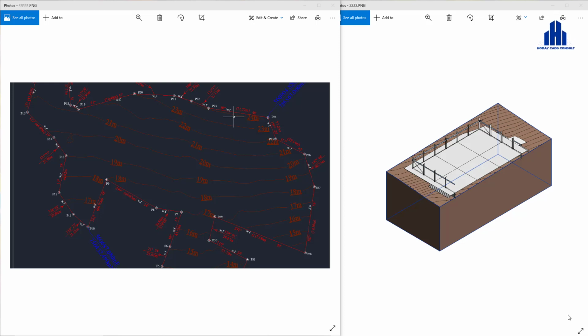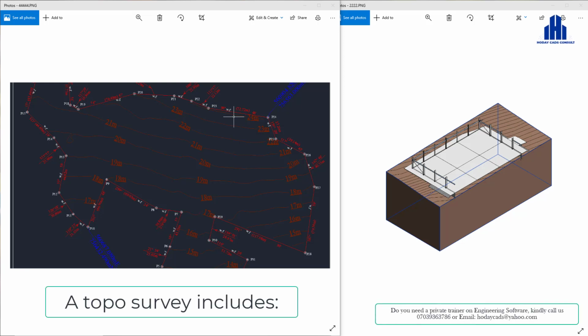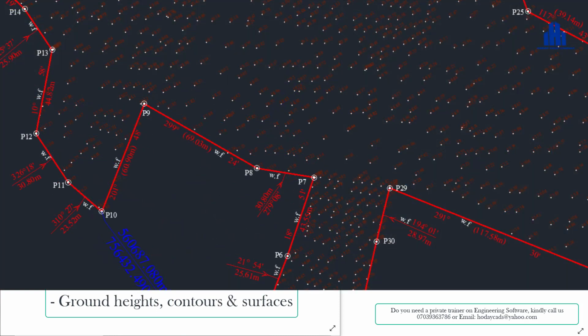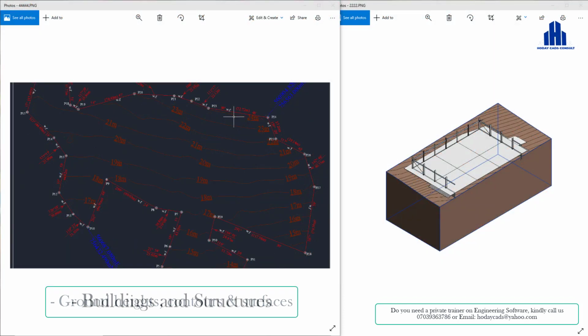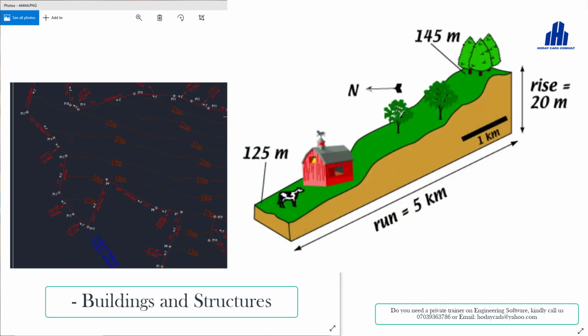So there are quite a number of documents a topographical survey will provide, but a few of them, which are the most important parts, are: one, the coordinates of the site or the land; then the spot height or the elevation of the land, which talks about the spot height of each point on the land; and the contour lines that show how sloping the land is. Then the final part is the existing property features, the physical features that are existing on the site, either natural or man-made.